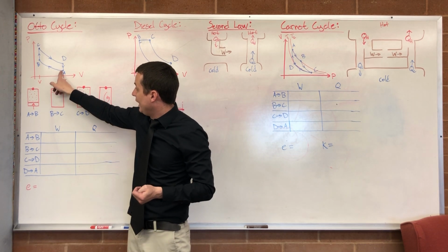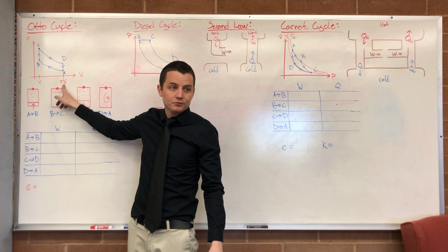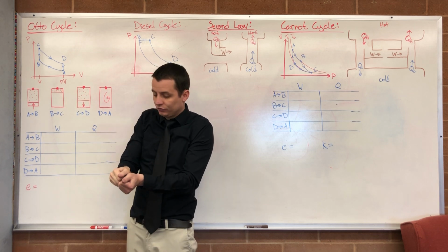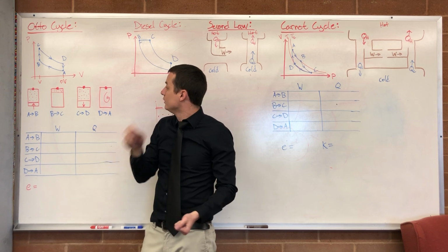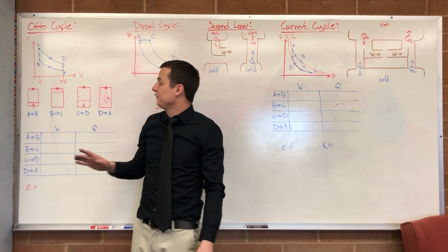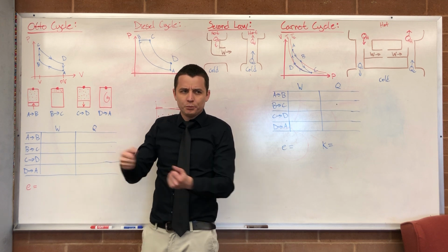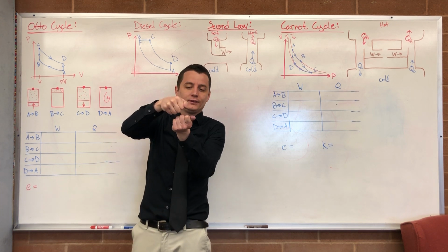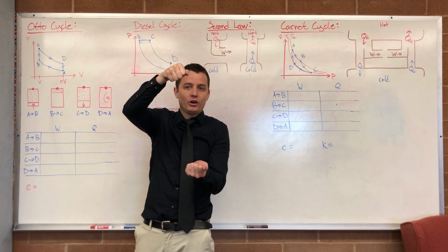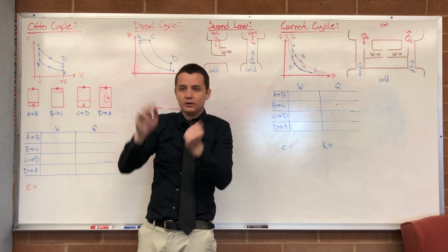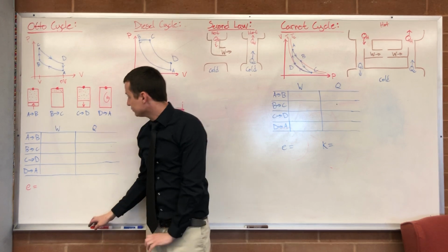So, starting at A, notice your piston's volume goes from V to R times V, where R is the ratio your volume increases. So ratio, not radius. For a standard car, I think R is somewhere around 8. When your piston expands, at its most expanded point it has 8 times more volume than it does at its most contracted point. I'm not sure what those numbers are, but I think it's usually around 8, maybe closer to 10.